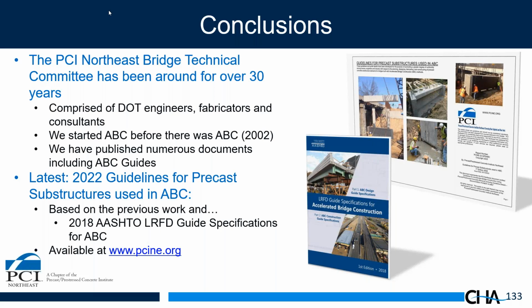Yeah, I like this question. Our committee was concerned with, you'll notice the earlier version of these guide details included a lot of precast footings. Our fabricators made it clear footings can get very heavy, very difficult to move, and very expensive to move. So it's not just shipping it, it's also what size crane you need to erect it. So we have given guidance on keeping the weight of these pieces down, and we have a recommended maximum weight, around 30 tons we recommend.